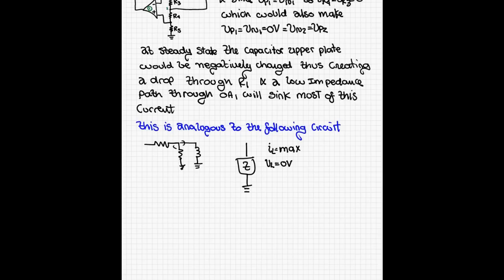I actually used this simulated inductor for graphic equalizers to design bandpass filters for every stage, and it works pretty nice. The only recommendation is to get a dual package or a quad package so that those op-amps are very, very well matched. So that's it for simulated generalized impedance converters.